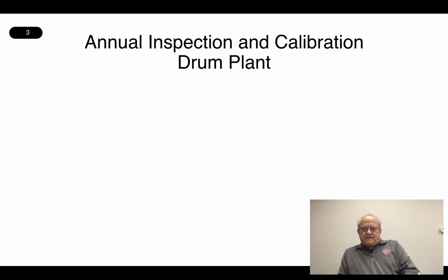So you've been in the labs, you've seen how they put asphalt mixes together, designs, and in the real world, in an 8-hour day, you're going to put together a little over 100 pounds of material and come up with the design and say, great, here we go. Now we're going to hand this recipe off to the plants and say, here, can you make this for us? But the problem with it is, at the plants, you're going to make it 50,000 to 100,000 times faster than what you do in a lab. And it gets really complicated. And this is where the inspection and the calibrations come in on your plants.